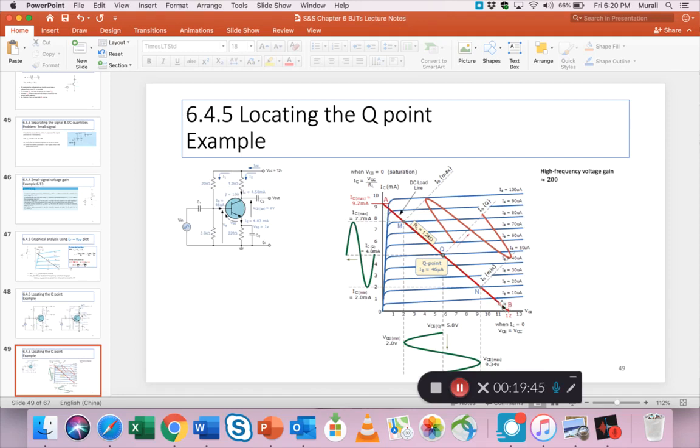So you plot that. All these blue lines, you get that from the manufacturer of the transistor. The transistor manufacturer will give you this drawing, or you can download it from the data sheet, and then you put your load line on it, and then you say, okay, right in the middle I'm going to pick my Q point, which corresponds to about 46 microamps, and then my base circuit current can go like that, right? And my output voltage VCE comes out.